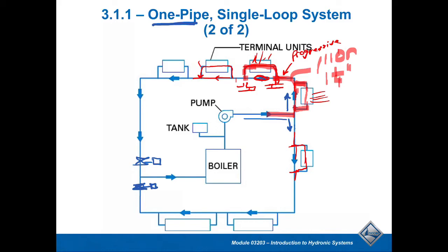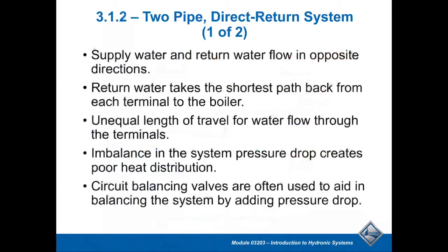So the same thing applies on this side of it. We scoot through here, go through here. These specialty Ts are creating a little bit of resistance between these that is forcing some of the flow to go through these circuits. So there again, that's a one-pipe main system.